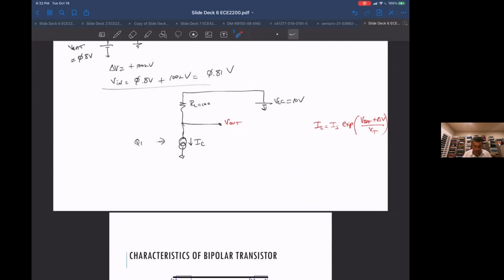So if you wanted to, in the lab, check what V out is, let's say you have a multimeter. I don't know if you guys have used multimeters or oscilloscopes. You need to plug something into V out, but then you have another connection on that multimeter or scope probe, which you have to hook up to someplace that you're comparing V out to. And again, when we don't say anything, you're comparing it to ground. So if you had a multimeter, you'd connect one end to V out and one end to ground.